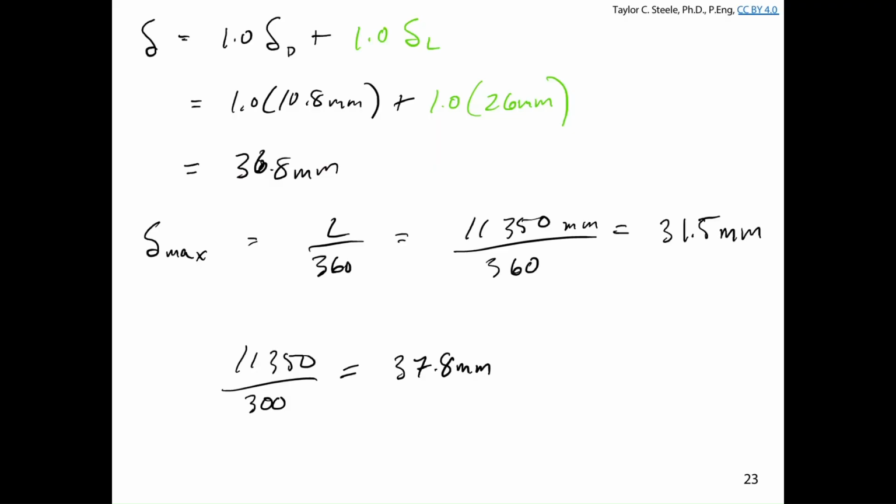Yeah, right? So there are a couple of things going on here. You need to understand what the floor system is going to look like. The architect specifies that, but you need to know, is it susceptible to cracking or not? Because that can change whether or not that joist is acceptable. You also have to know if the partitions are going to be a permanent fixture or non-permanent, something you can move around, because in that case, that also influences your design.